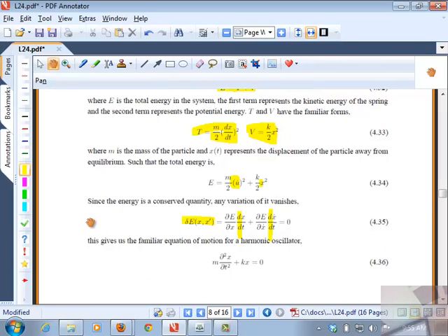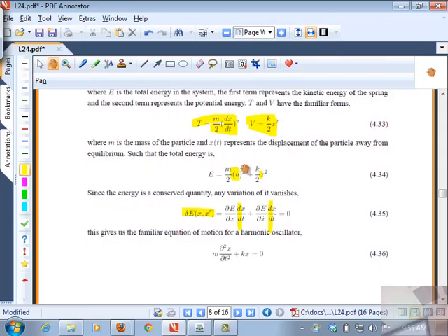You will see the relationship that in some cases, when you have non-dissipative systems, conservative systems, where there is no dissipation mechanism, the Euler equation being one example, and in solid mechanics there are the Hamiltonians. So these are all representations of some form of an energy, and the minimization of the energy becomes a natural way to express it, and your finite element method falls out of that, minimization of the energy. In those cases where it is not possible, we start with your equation of motion, and we form what we call the weak form of the equation, and we again convert it into an integral representation. Okay? So that's where these ideas converge.